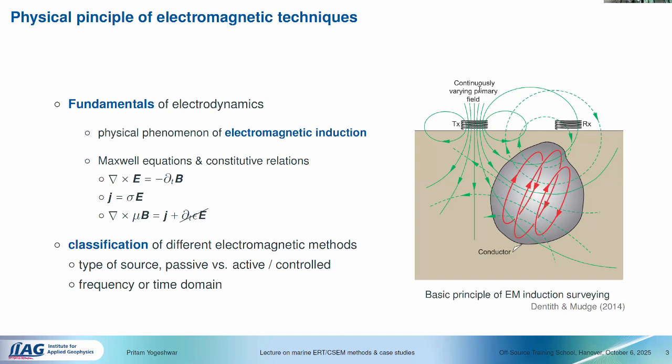And in the case which Mike presented, where we have stationary current, so direct current, ERT, all these time-dependent terms will vanish. And what's a bit special for induction methods, the diffusive methods, is that they are described by a similar equation as heat diffusion. We always neglect this term, so we are assuming slowly oscillating fields. That means everything in the subsurface vanishes, or let's say polarization in matter vanishes faster than the time span we measure in. This term is called displacement, so all displacement currents vanish. So we are only looking at this equation set.